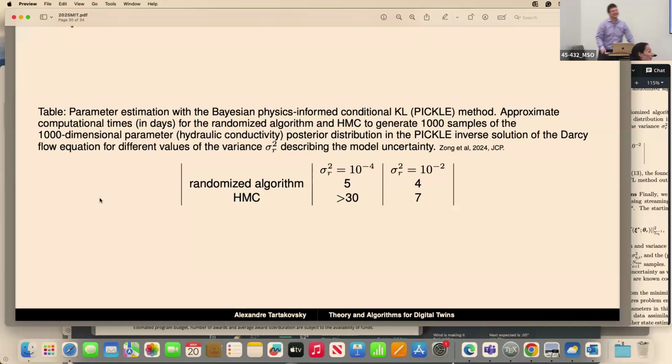Here you're doing a KL expansion for the control and the field separately. Yes. But by doing so, your leading mode in the control is not necessarily the optimal mode that gives you the optimal response. Have you considered doing a decomposition by taking the control data and the response data together, finding the linear optimal forcing mode and linear optimal response mode, and then doing your learning on those coefficients?